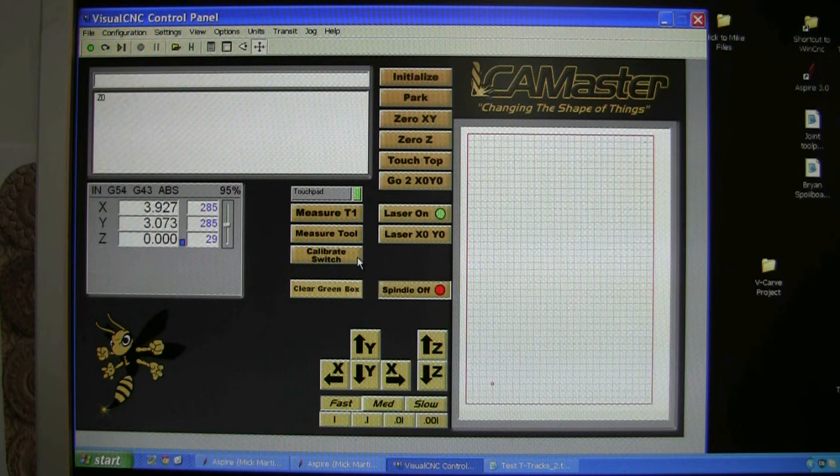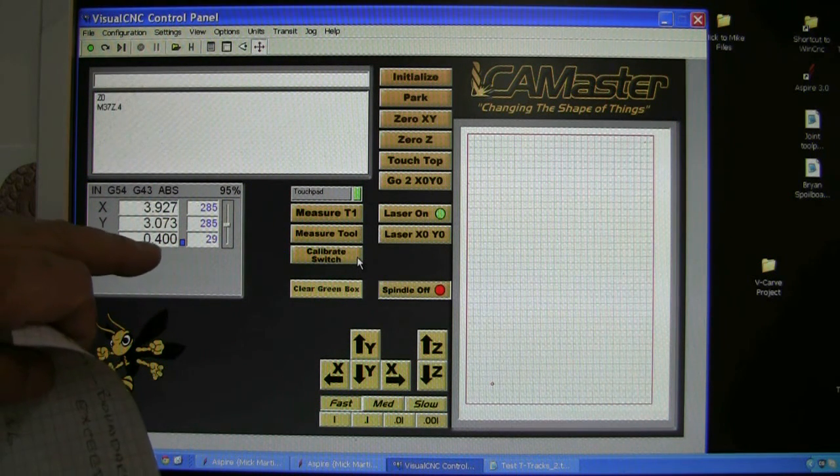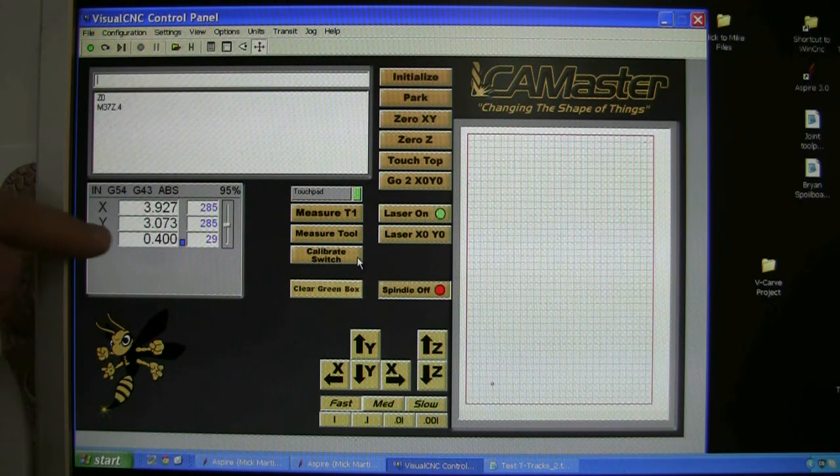So what we've got to do is basically trick WinCNC, well not trick it, but we've got to lower the blue box. So the way you lower the blue box is type in M37 Z, I'm going to go down 0.4 of an inch. So if I hit that, WinCNC, now the blue box is set at 0.4. I'm on my spoiler board, but it's really 0.4 above 0.